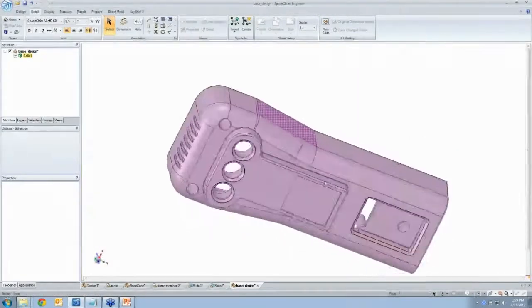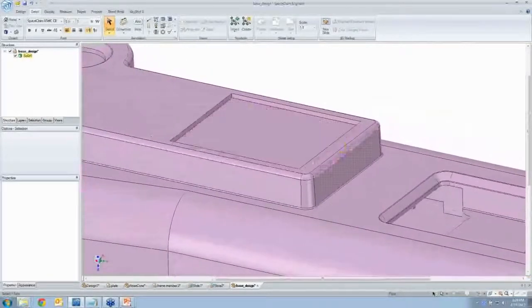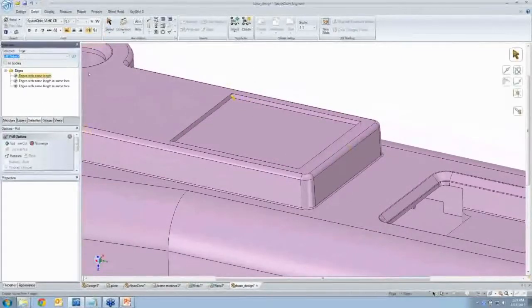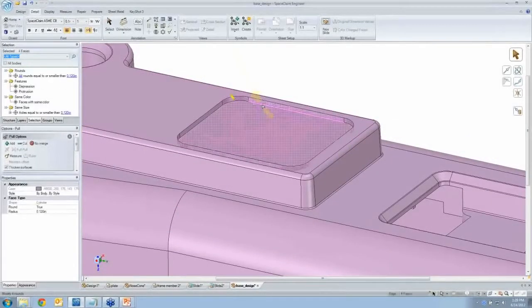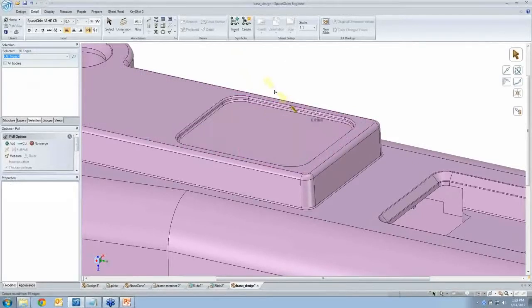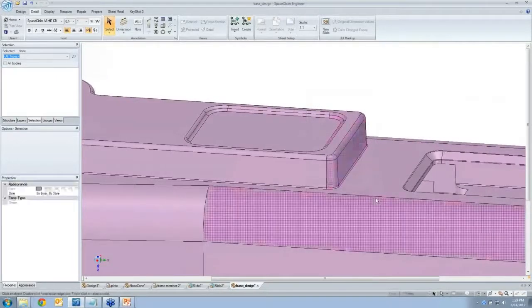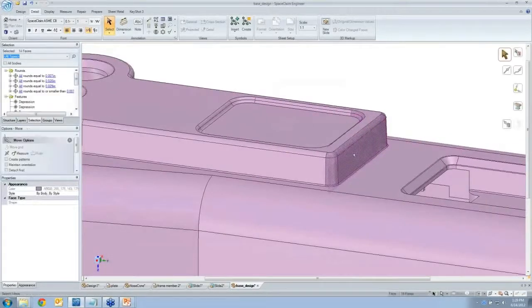Step file, again, I can't stress the importance of it. I don't know how this model was created. This is just dumb 3D geometry to me, but I can go in and start making modifications anywhere I want, add some rounds to this. You know, maybe the point is I need to make this thing more manufacturable. Someone gave me a model that's close to being manufacturable, but it's just got to have changes on it so that there's the proper draft everywhere. Again, anything I need to modify in here, I can accomplish. If I need to change the actual distance of this opening, right? I go move some faces around.